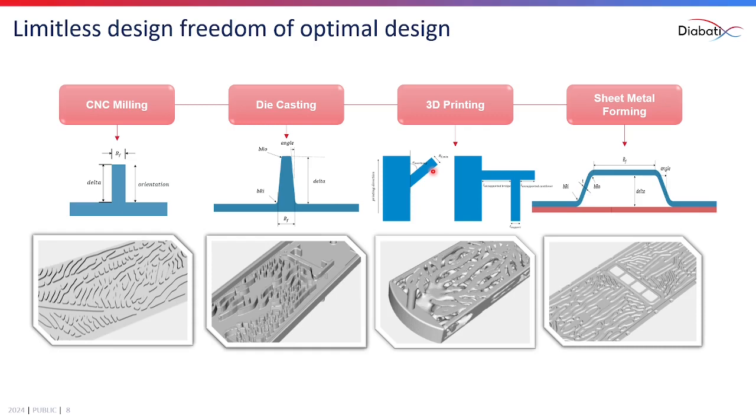Colsim takes manufacturability into account from the start. So as a user, you can dictate what kind of structures Colsim can consider. For example, in the early design phase for purely prototyping, you can ask Colsim to generate 3D printed or CNC designs. Or if it's for mass manufacturing, then you can ask Colsim to generate structures using the die casting or sheet metal forming constraints.